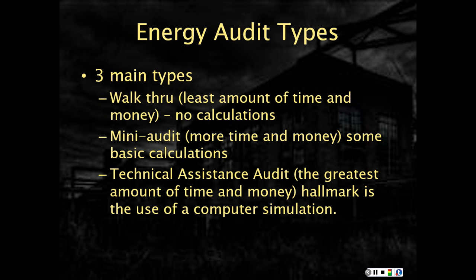In general, this means that you're going to walk through the building and look for probably the most obvious things. The hallmark of this audit is we don't take any time to sit down and do any type of calculation. So the audit takes the least amount of time and the least amount of money. It also provides no real in-depth analysis of what's going on. A lot of times a walkthrough audit will be used to decide if more money should be spent on a more elaborate audit.